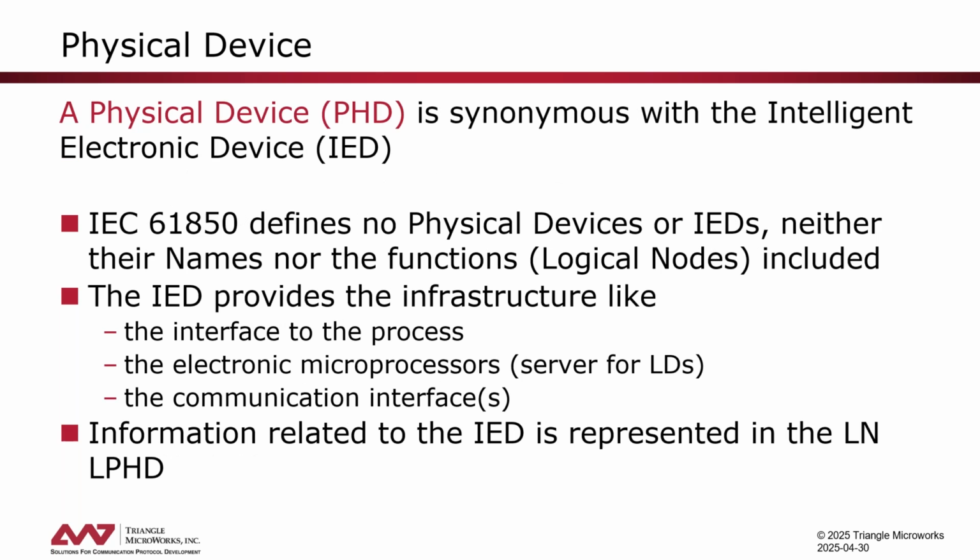We also have physical devices, as we mentioned, which is basically the same as an IED, an intelligent electronic device. Again, the standard does not standardize IEDs, like what functionality should be grouped together in a device. This is an issue for the device manufacturer to build the devices as he thinks is useful and group the functionalities in.